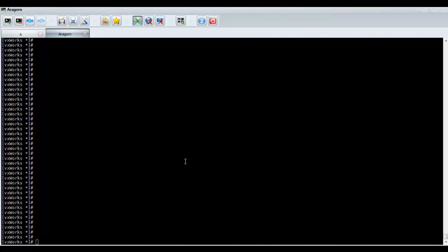What I'm going to show now is essentially the same process of connecting to the DTP4500 and deploying an application. But this time, instead of using the SCA monitor in Spectra CX, I will perform all of those actions using the OE admin tool that comes with the Spectra core framework. I still have the DTP4500 board running, and it is running the platform model.